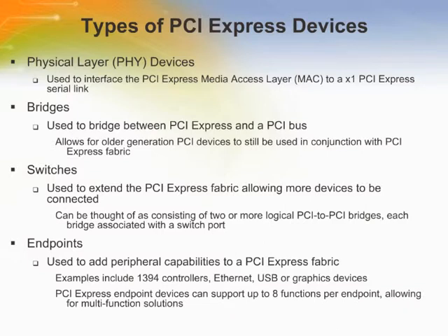TI offers 4 different types of PCI Express device families, including physical layer or PHY devices, bridges, switches, and endpoints. PCI Express PHY devices are necessary when FPGAs in a system design do not have the functionality integrated. Connecting a PHY device to an FPGA allows the FPGA to then be part of the PCI Express fabric, and in turn can take advantage of the higher speed and bandwidth capability of the architecture.